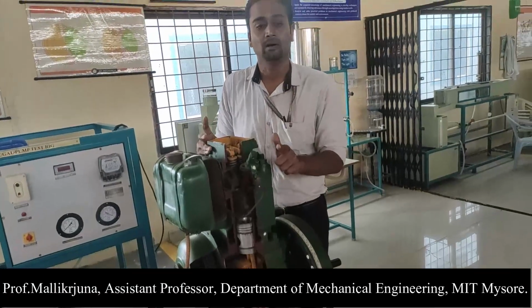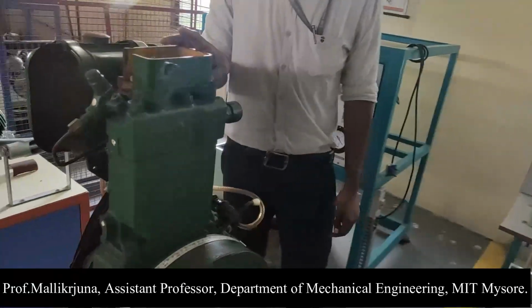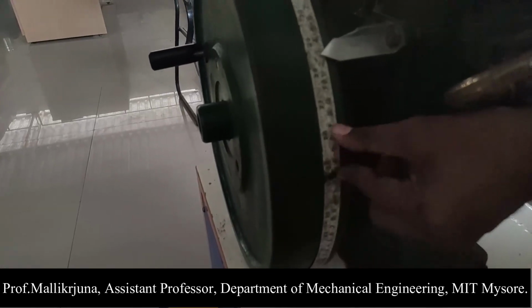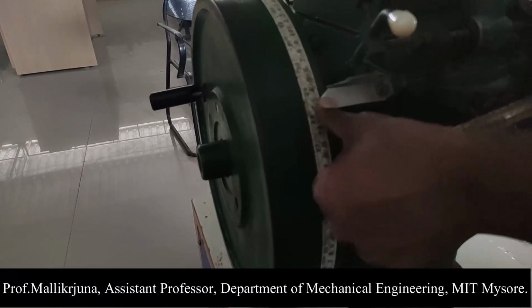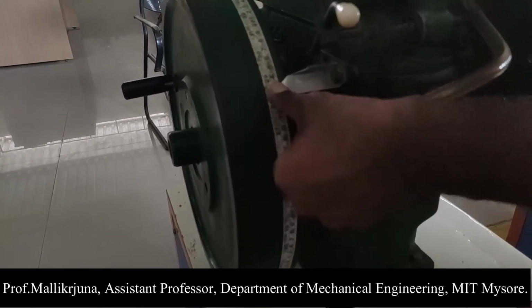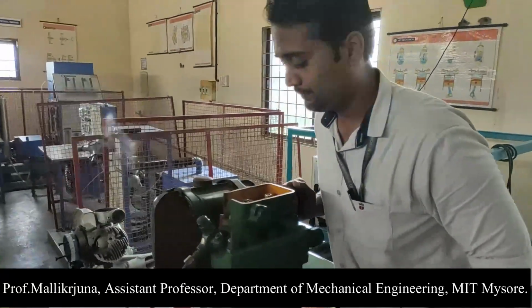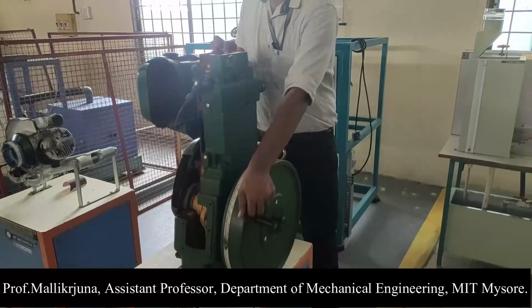If you want the reading on the flywheel, please come to the side. If you clearly look at the mark over here, this is the BDC mark. Below this is before BDC, and after this is after BDC. So I have crossed the BDC by this much reading. That means the inlet valve has been closed after BDC. So one of the values is fixed now. Let us continue the operation. Now I will continue the rotation that I am giving to the flywheel. The inlet valve is not moving.